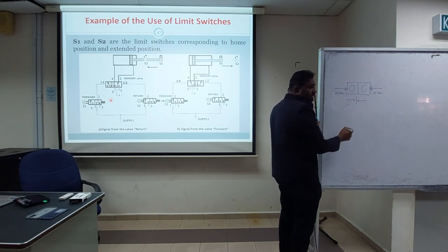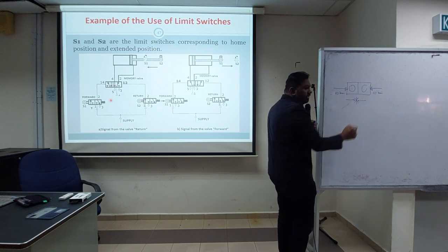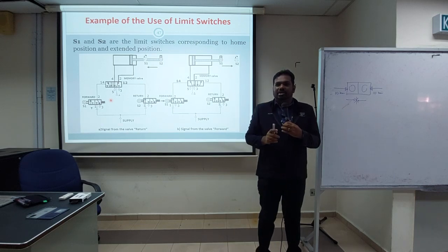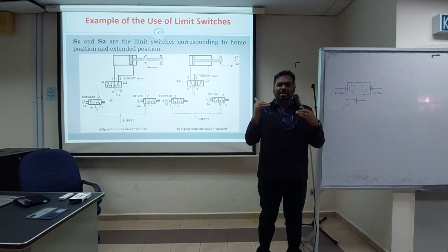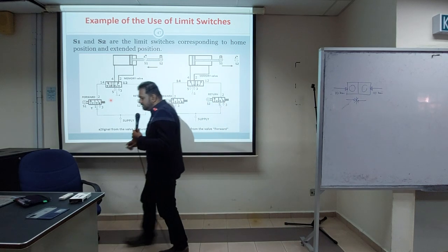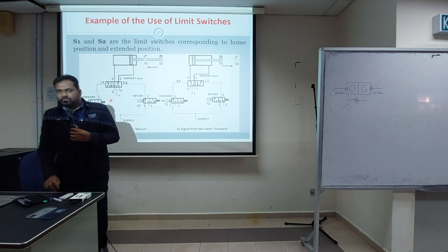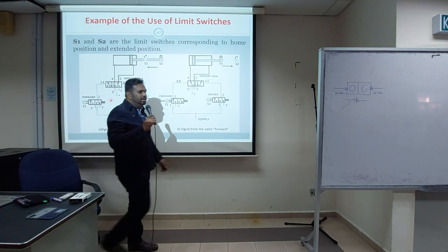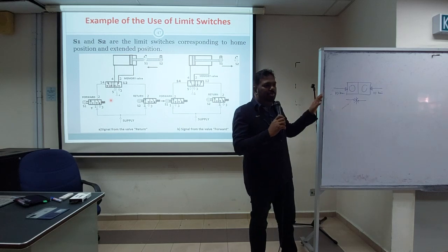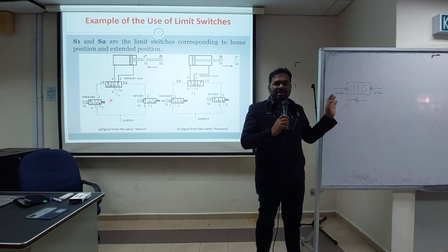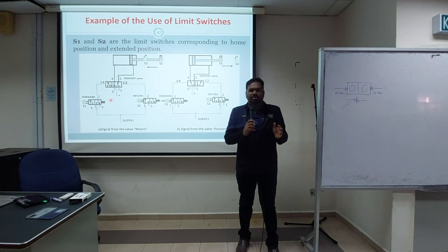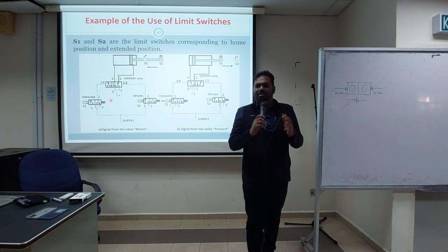So it will cancel. It will not extend or retract, because the pressure will be the same. So in a case where there's a signal overlap, your cylinder will not extend even though it gets input from both sides. So both sides get input, but the cylinder won't extend because it cannot decide. Because it is not smart, so it cannot detect.